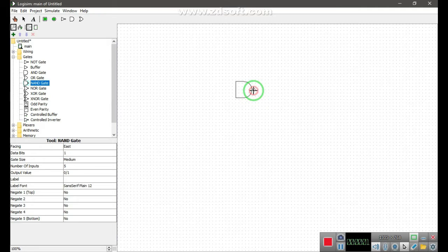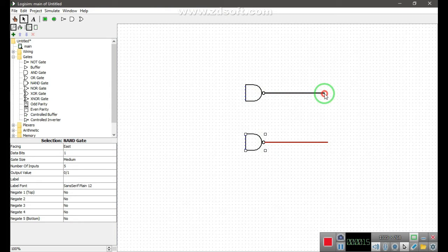The simplest way to make any basic single-bit set-reset SR flip-flop is to connect together a pair of cross-coupled 2-input NAND gates as shown, to form a set-reset latch, also known as an active low SR NAND gate latch. So there is feedback from each output to one of the other NAND gate's inputs.